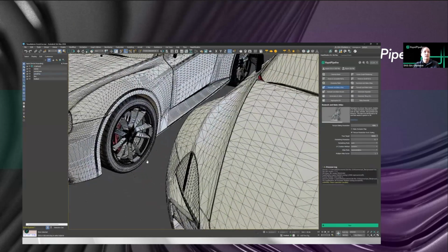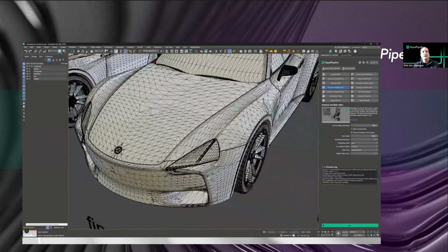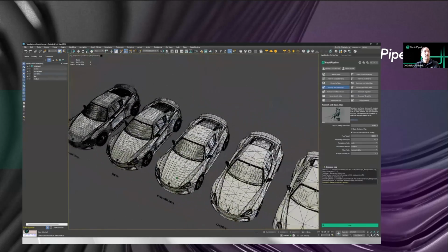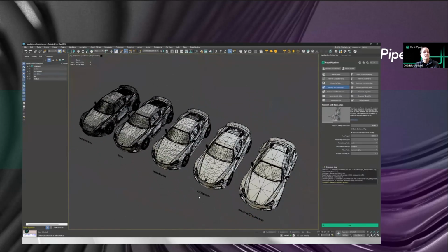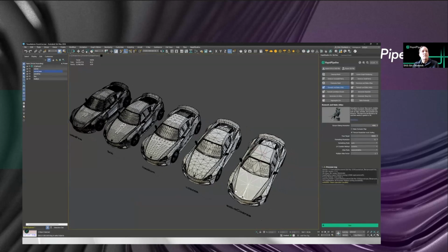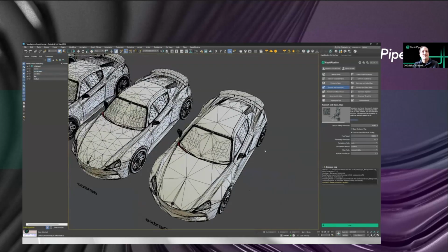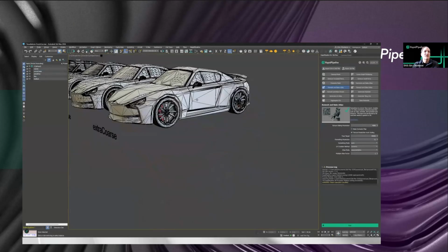If you're getting in close up to various surfaces and you don't want any chunky renders going on. In general, when you're optimizing files and getting them out for web output, you don't want multiple millions of triangles. You want to get down to something that's under, say, 250K triangles or so, just to make the file size manageable and to make it render fast. And you can go automatically to extra coarse, the lowest level of detail by default, but you do get a chunky look to it.